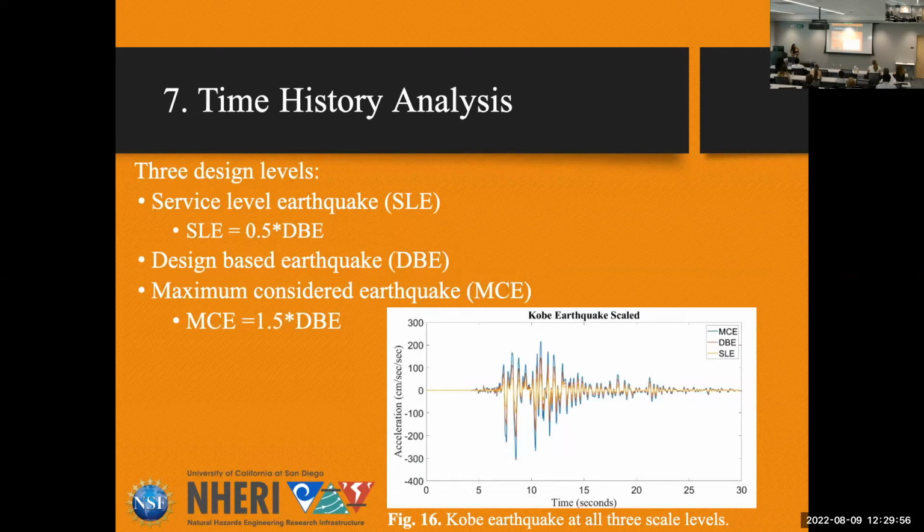So then what do we do with this information? We run a time history analysis of the earthquake at 3 different levels: the service level, the design base level, and the maximum considered earthquake.